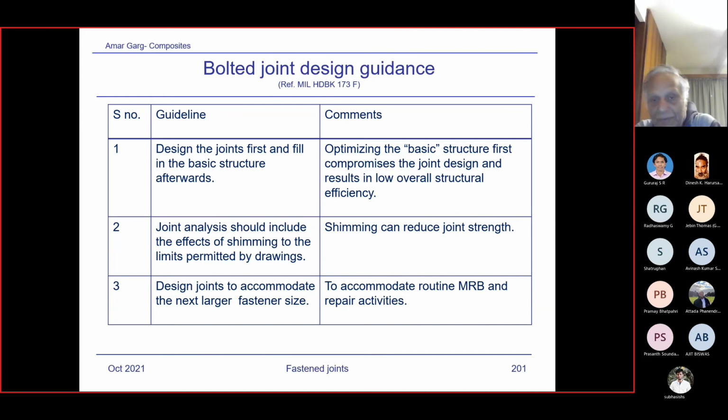So minimum shim which you have considered in a design, effect of that has to be considered in static and fatigue margins. And the drawings will be showing that shim allowance. Whether shim is there or not, don't worry about it. But you are allowing the design to have the provision by the production for the shim. And the margins would be lower with the shim.